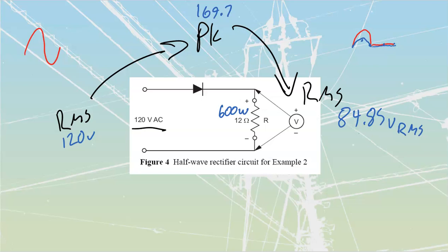Which means that if I take a look at my volts times my amps, I've got amps and volts. Over here, they're going to be at a value of 0. Over here, they're both going to be at a peak, so I multiply those together to form a peak. Over here, they're back to 0, and once again, we play connect the dots, and we see that we get that power waveform. But now we only get half of it. Remember that before on our previous circuits, we had a power waveform that looks like that there? Now we have chopped that all up. Because we get no volts, we get no amps. If we have no volts and amps together, we get no power together. So we're losing half of our power. Really, that's what's happening inside of here. Let's just erase that because we've lost that half there. What does this mean? Well, take a look at the value that we just calculated. 600 watts over here.